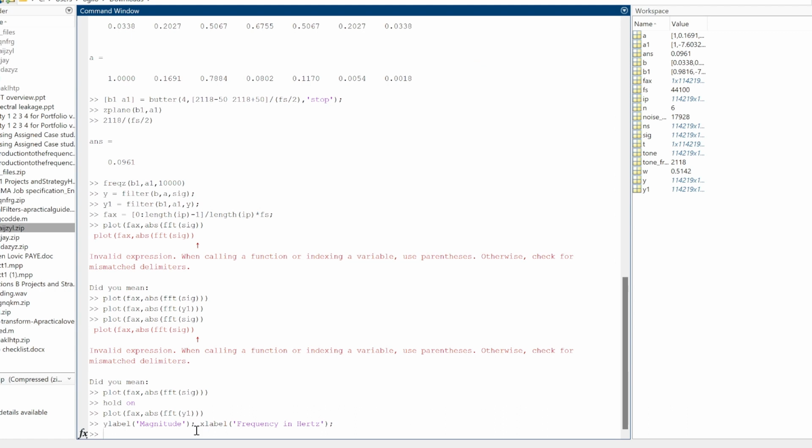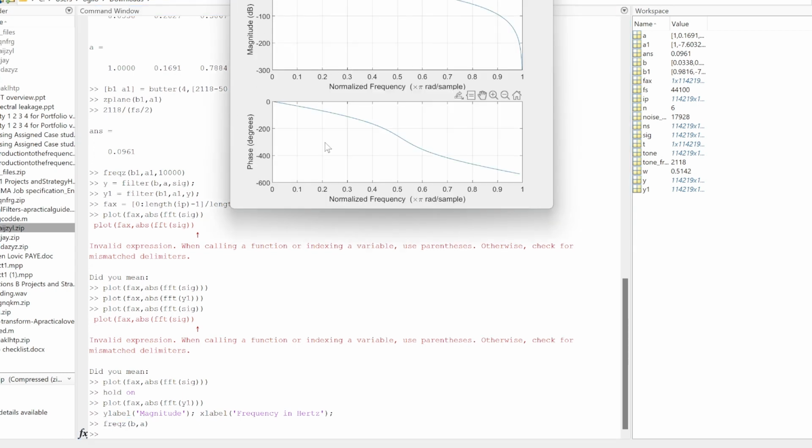Now we're just going to get the frequency out of B and A. Let's see what radians component we can identify here in the phase. So this is already in degrees here. Going to zoom in. 45 degrees. So I'm going to move across, look for a shift of at least 45 degrees. So probably around here, I'd say. It's 44, so we need a bit more.